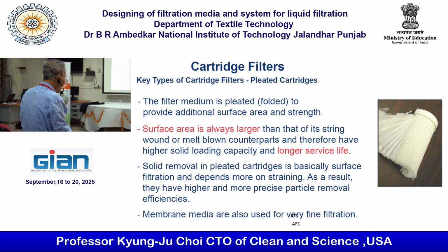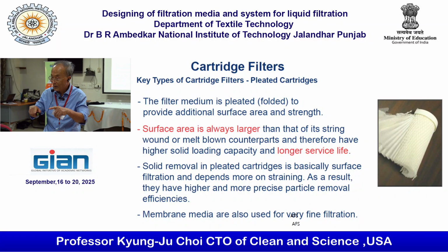Here, I can tell you one thing. The design of the pleated cartridge filter: now they have a lot of different shapes of cartridge filter. The pleating is not very regular like this. It has a lot of variation, one small, the other one big, something like that. Because in liquid filtration, the pressure is higher, that's why you need a special arrangement of pleated filter.